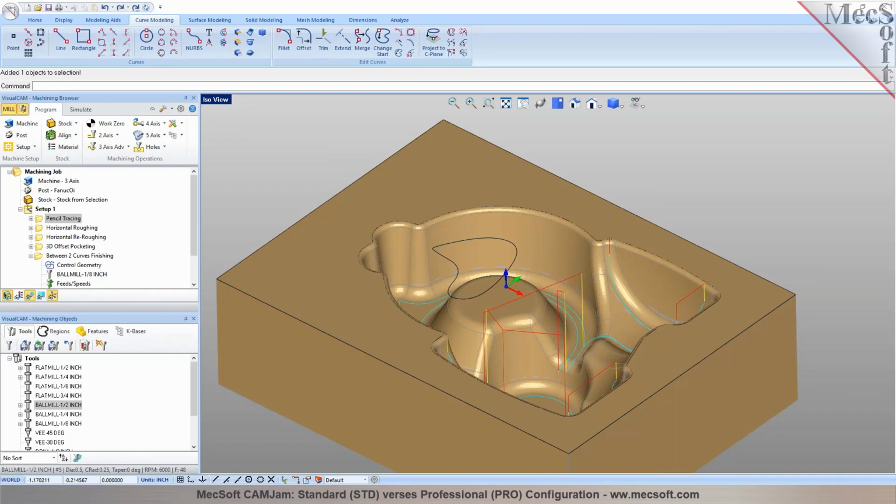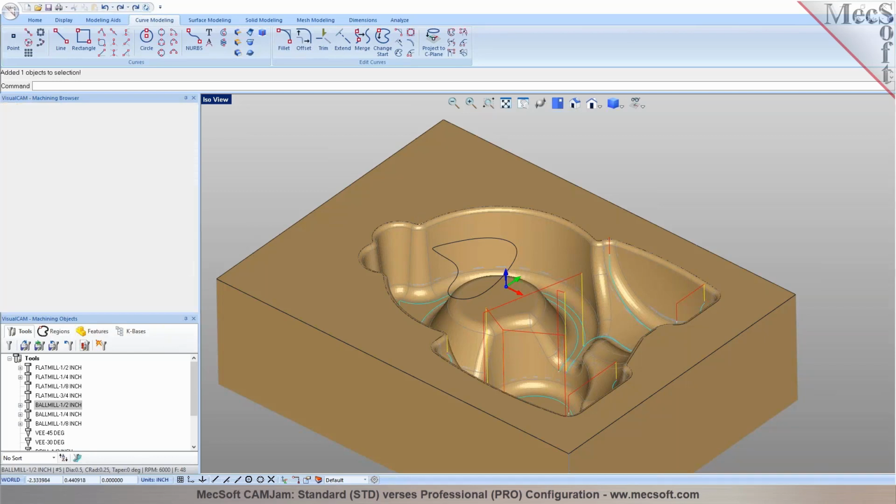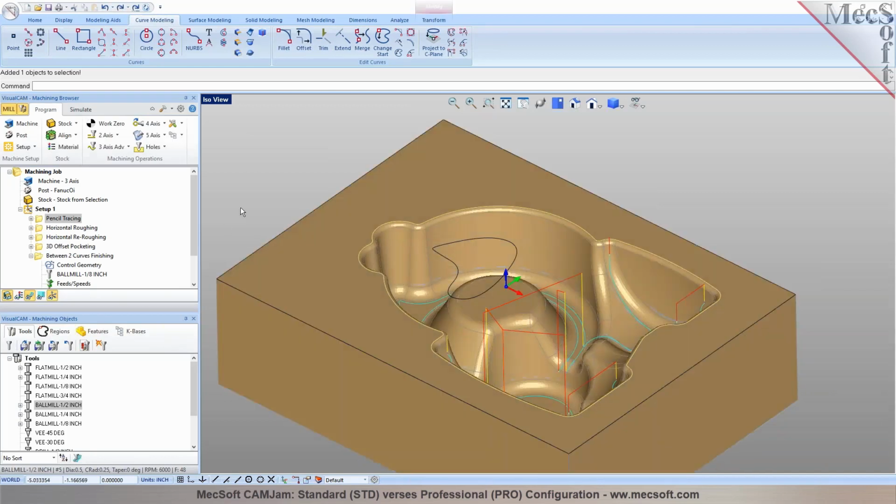Are you trying to do an additional compensation for tool wear, or are you looking to do a G41 or a G42, which is typically done in a two-axis operation? Yeah, we'll just say some of this part that you have on the screen right here, like this large curve in the back. Over here? Yeah. Okay.